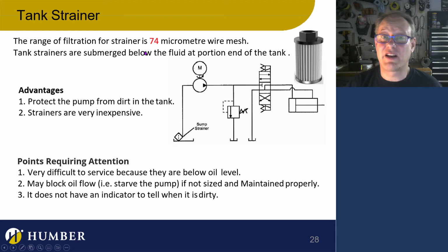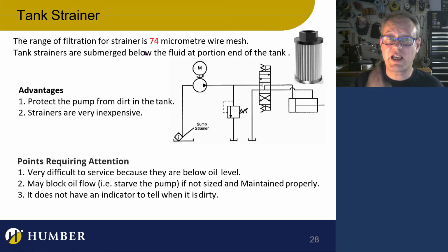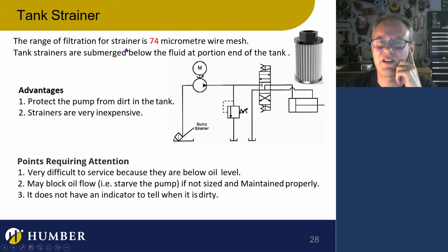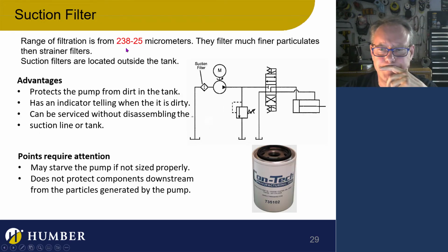It's not actually going to get dirty unless your tank is filthy. And if your tank is filthy, you've got to go get a kidney loop and put it in there, or you just have to pull all the fluid out of there and replace it. So your strainer isn't going to get dirty, because you're keeping your fluid clean, and all of the other filters in the system that are outside the tank are doing such a good job that your strainer doesn't get dirty. So you're not going to have to replace it.